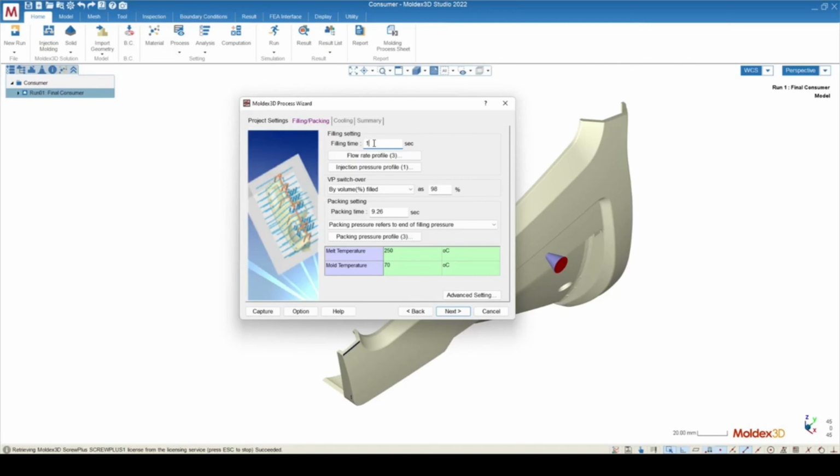We already know what the fill volume is going to be, what our injecting volume needs to be. So when we define this filling time in seconds, that allows the software to calculate the initial flow rate of material into your geometry. Based on how that material flows into your geometry, whether there's shear heating or hesitation or some other flow inhibiting or flow acceleration phenomenon, the output filling time from the simulation might be slightly different than the input.